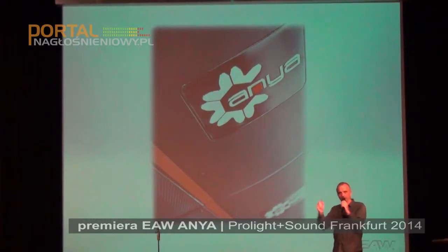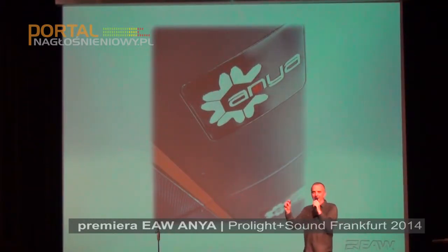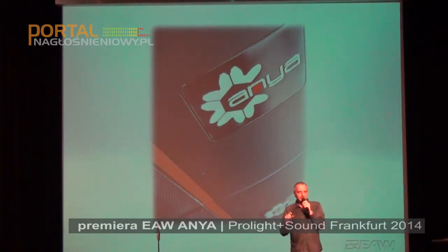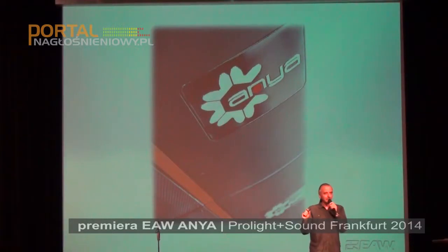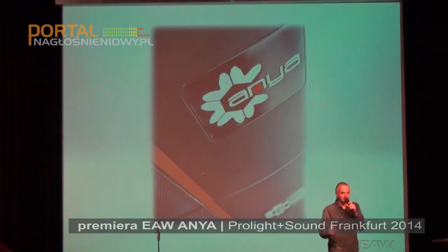If the device falls within that plus or minus, it will indicate the device passed. If it doesn't, of course, it will indicate that the device failed. This doesn't mean that the device is not working. It may simply mean that the device is tired. It's been worked hard. It does not comply anymore with frequency response against the factory stored curve. So it's time to change that device.